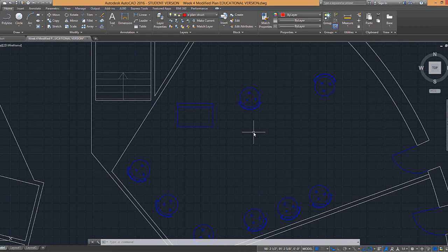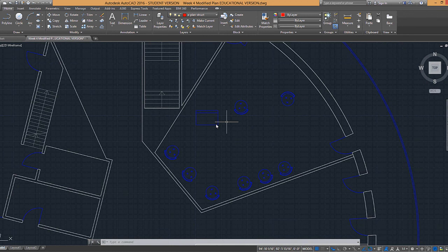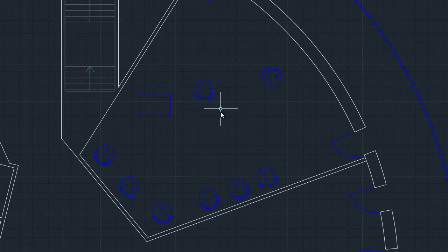Again, it's going to be a line weight issue, but also you'll find that you get a lot of block resources from other places. The problem with that is that a lot of them don't follow that methodology. So when you insert one into your drawing, it doesn't take on the properties of your layer. Being mindful of that will allow you to fix that problem and have those blocks from exterior resources be coordinated with your drawing.